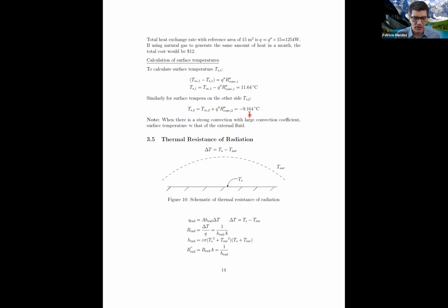Very interesting. Okay, so we just talked about the outer surface of a wall in which the convection cools it down to pretty much the same temperature of the fluid outside. But inside, the convection is natural convection, is very weak and gentle. So that acts as an insulator. And we had a significant temperature jump. If the temperature of the room inside was 20 degrees, the temperature of the wall, of your brick wall, when you touch it from the inside, would be at 11.6 degrees.